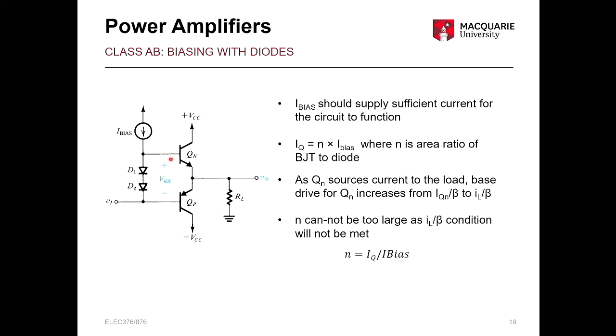And this is something that in discrete circuits is very hard to control, because you can't just change the junction area of your diode. But if you're designing an integrated circuit where all of this is strictly designed at the semiconductor level by you, then you can control that junction area. So power amplifiers can obviously come in ICs, and they'll have all this design taken into consideration.